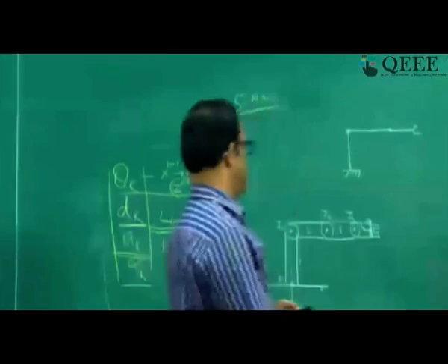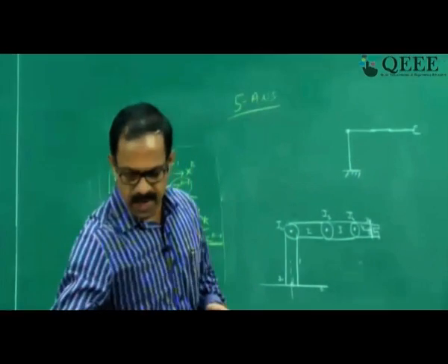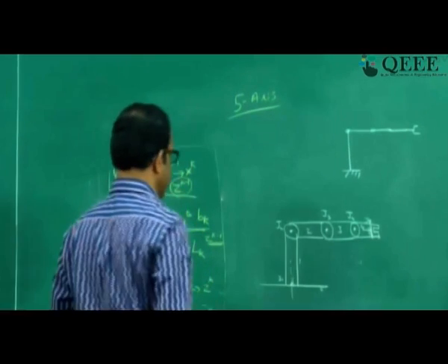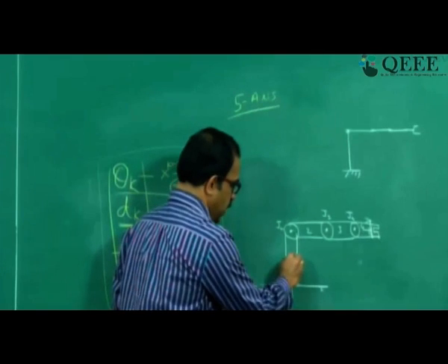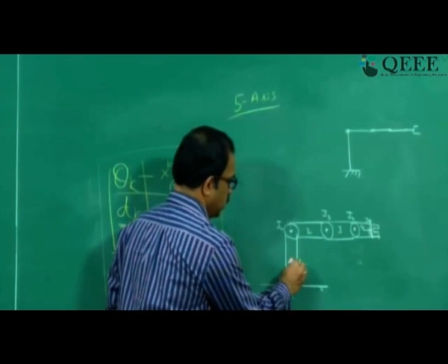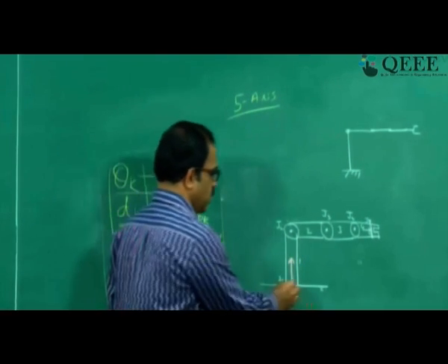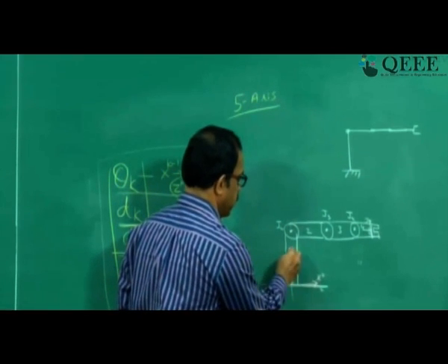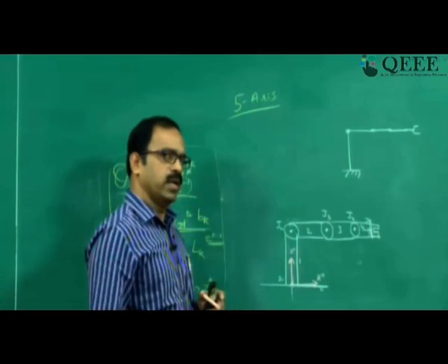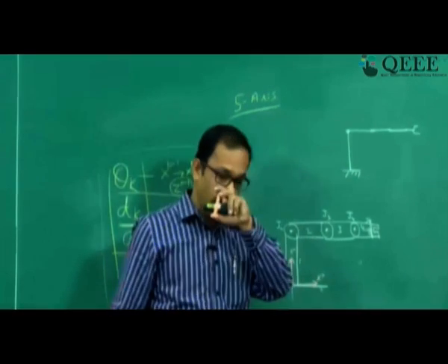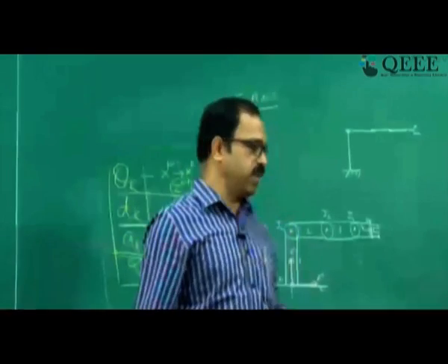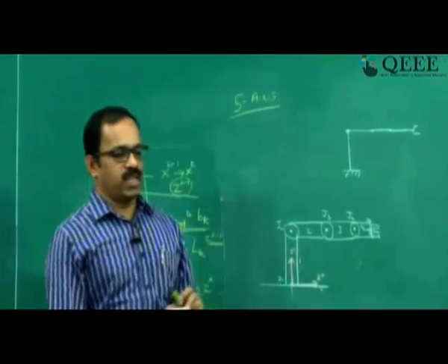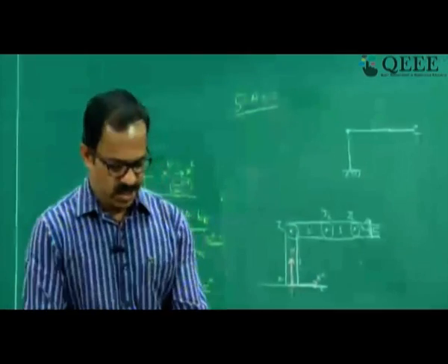You assign the joint numbers and link numbers, and start with the base coordinate frame. As I told you, the z axis will always be along the joint axis, and x will be assigned the positive x direction. So it will be x0, z0, and then a right-handed coordinate frame. Now you can assign a right-handed coordinate frame at this point. X0, Y0 shown here. Find out what the y direction will be.